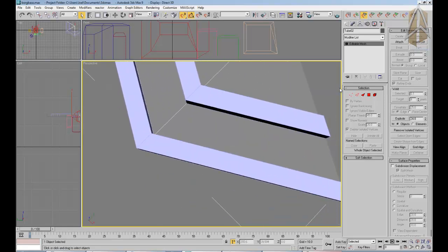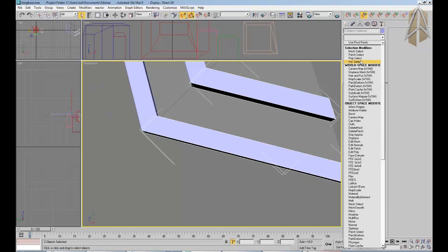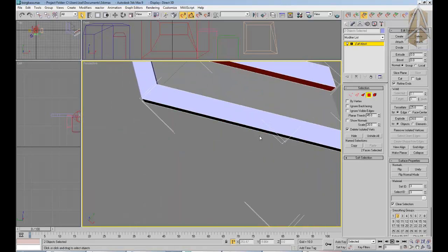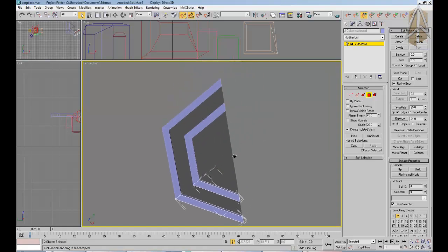Got everything deleted. Now I start modeling this connection by creating 4 new vertices where I can draw new polygons from. This can be done in plenty of different ways. I just choose here to use the slice tool. I selected 2 polygons that are going to be affected and slice them at the part where the new connection is going to be established.